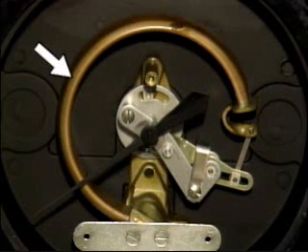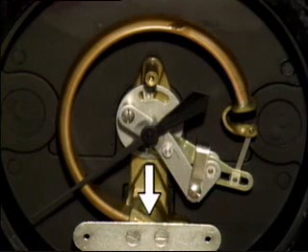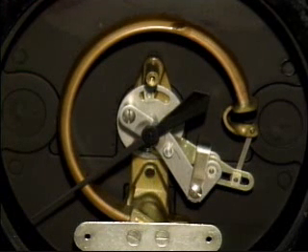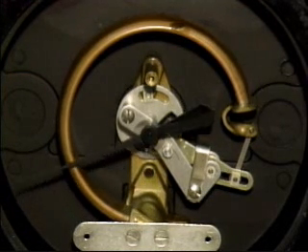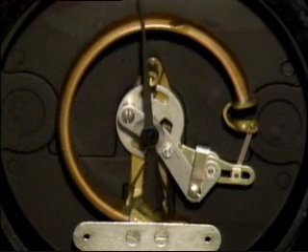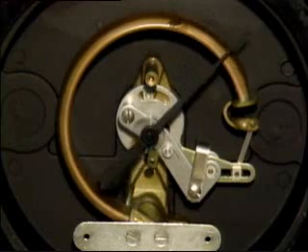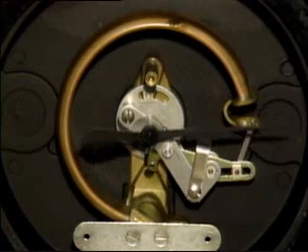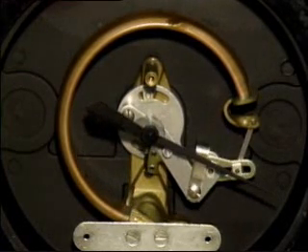This is a C-type bourdon tube, named for its shape. One end of the bourdon tube is attached to the pressure source, while the other end of the tube is closed. When pressure is applied, the tube tries to straighten out. The closed end of the tube moves in proportion to the amount of pressure applied. A mechanical linkage converts the movement of the tube to pointer travel.